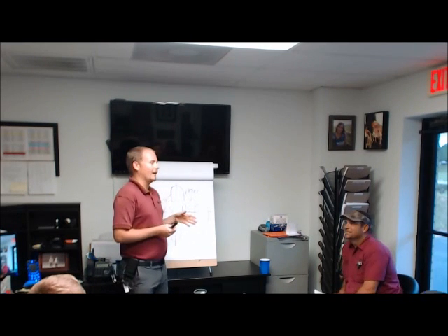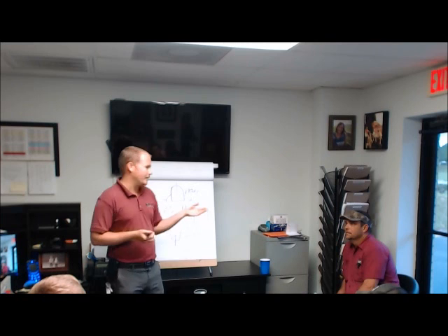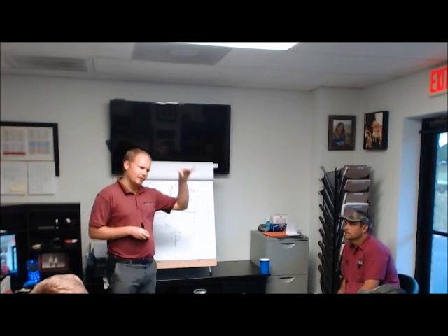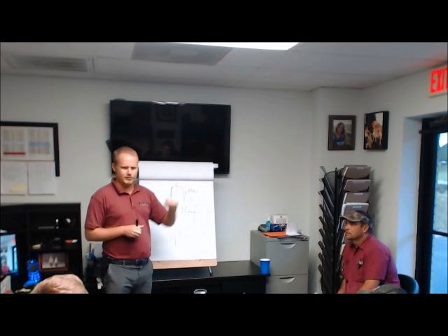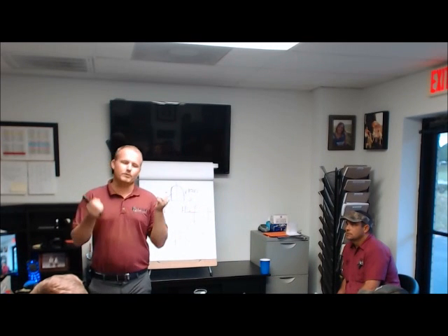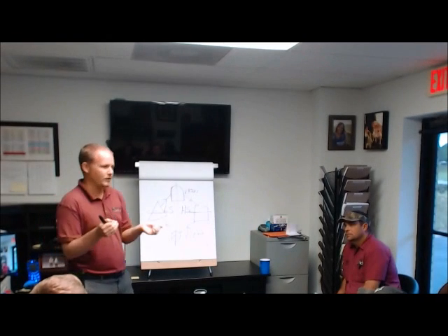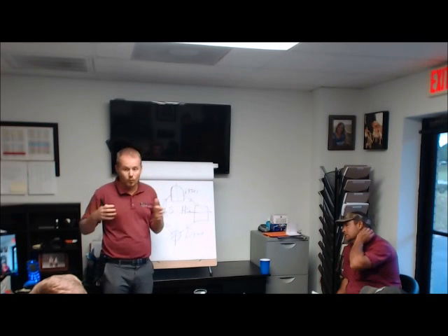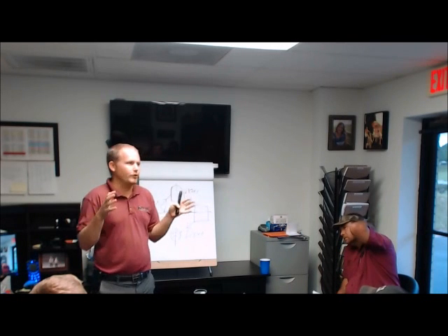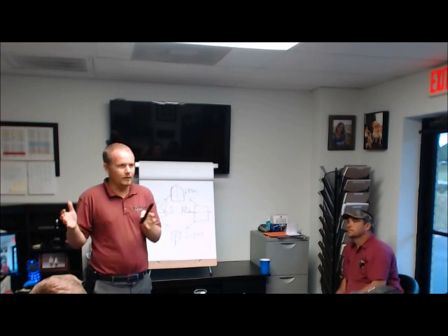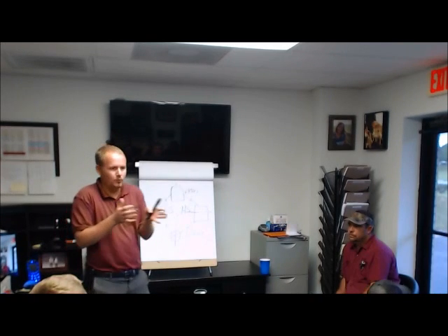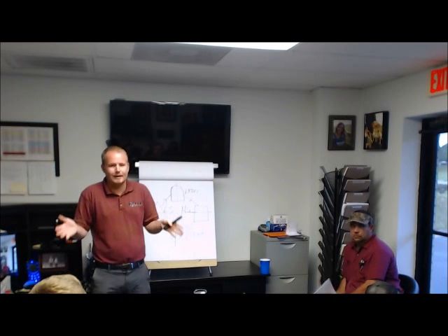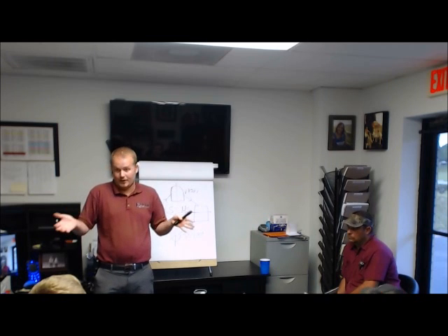A lot of people, I used to even teach this back when I was stupid. I used to say 1 degree of subcool is actually the ideal subcool to have because that way you're running your lowest potential head pressure, and lower head pressure is good because that means less amperage. Wrong, because we're dealing with matter here, and the matter that we've got is a refrigerant, and the higher the subcool, the more density we have overall, meaning we're actually moving more refrigerant overall. The more refrigerant you can pack into a system, the more cooling capacity you're going to have, because we're talking about cooling capacity per pound or ounce or whatever, per weight of refrigerant. And so the more refrigerant you get into a system, the more cooling capacity you're actually going to have.